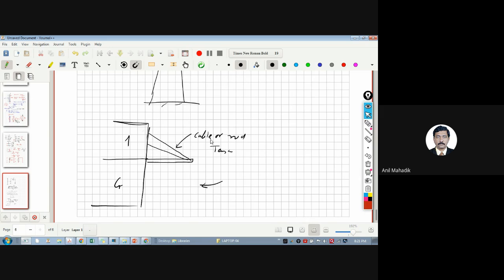So these are the general examples of tension and compression members. Any other example? Bracings, yes, correct. If there is a horizontal load, then we have a tension here and we have a compression here, right? So this diagonal will carry tension, this diagonal will carry compression. So bracings, yes.